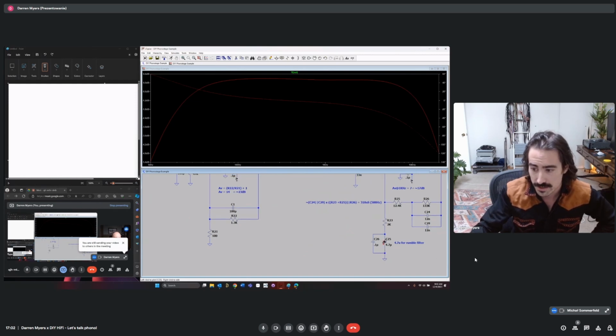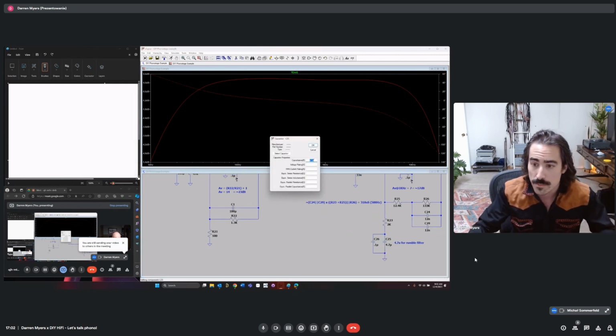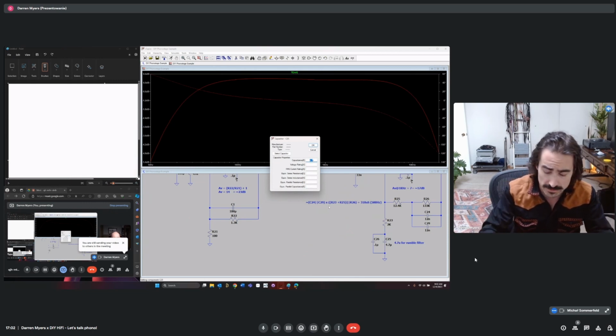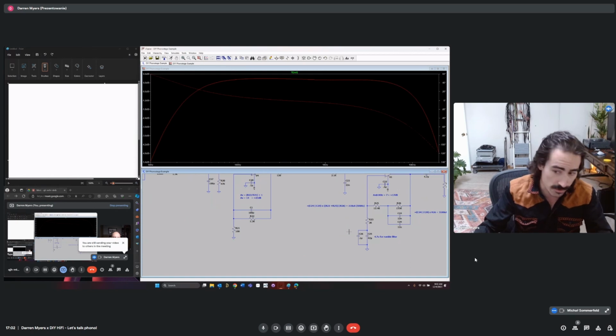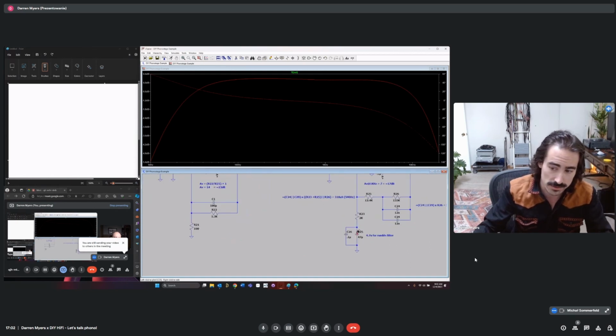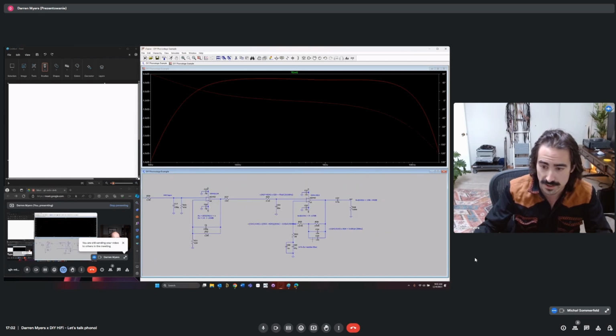Huge capacitor. A big capacitor is doable, but are you going to be able to find quality capacitors at that value? And what about money and size? They're going to grow in size, and maybe you're going to have to settle for a less superior construction. You're probably going to have to go electrolytic at that point, where here you could find a combination of parts to make things work.